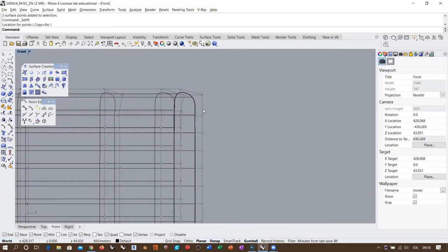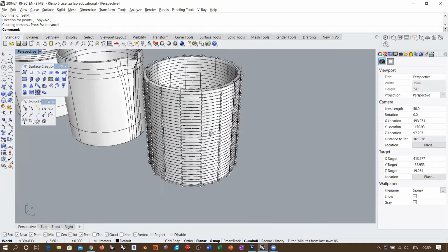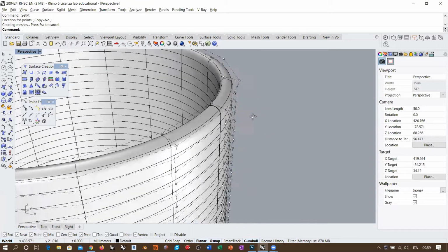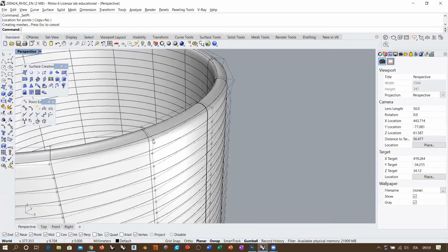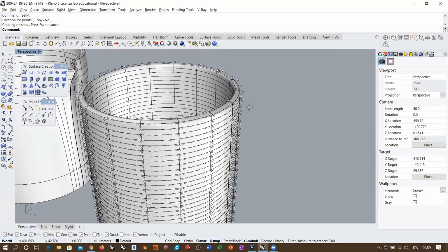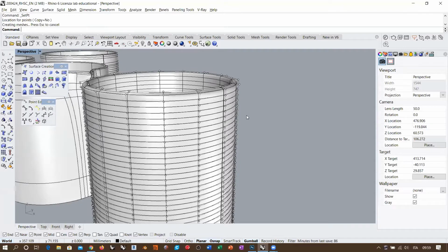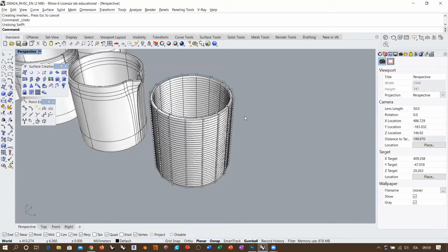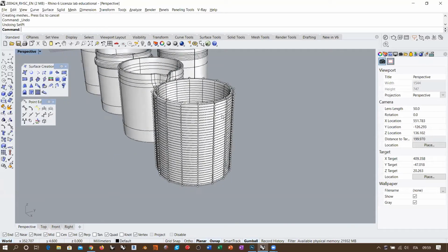But this is not enough, because actually this line belongs to a very complex surface. So I only took care of these 3 control points, but I still have this one here and this one here and all the rest around these rings of control points. So this is not going to be easy, okay, to regularize this kind of situation, right? This is why I do not recommend to make a rebuild of this surface.